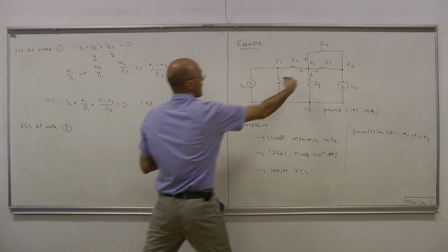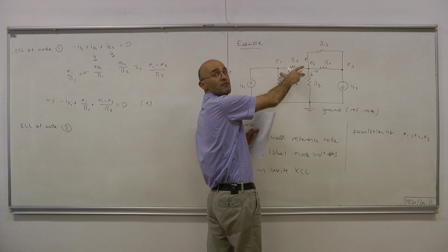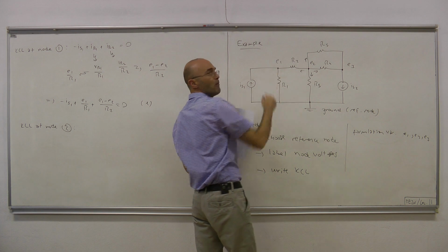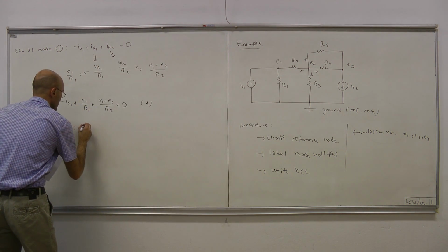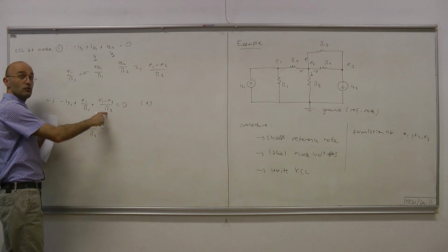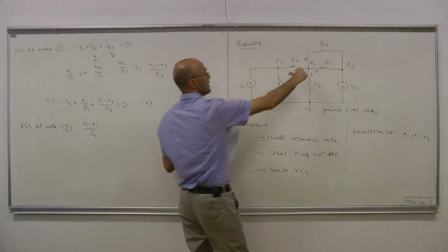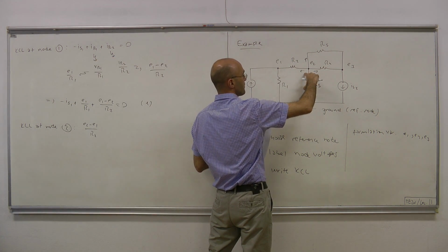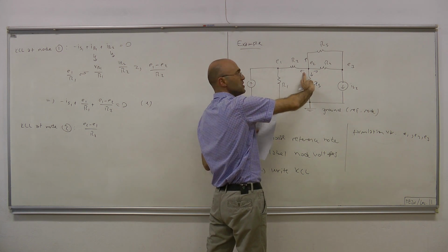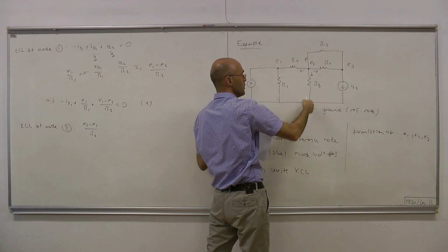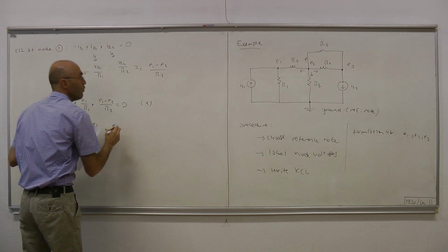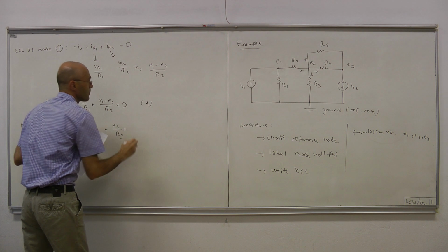So this current is this voltage, plus minus, over R2, and this voltage is E2 minus E1. Therefore, E2 minus E1 over R2, which is the negative of the previous current, is simply that current. Then we have this current, which is this branch voltage over R3, and since this branch is between node 2 and ground, the voltage simply equals E2, so E2 over R3.